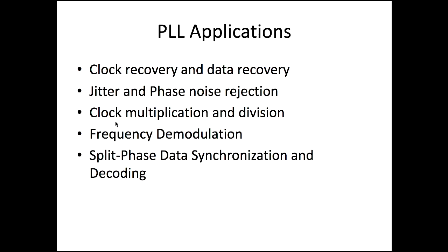You can also do frequency demodulation. Then split phase data synchronization and decoding. So these are the main applications of PLL, and in DSO you will be using a PLL for clock multiplication. But I will also touch upon some of these applications. I think apart from clock multiplication and division, frequency demodulation is widely used. Then clock recovery and data recovery, again widely used. Maybe I will touch upon those three applications when we study PLL.